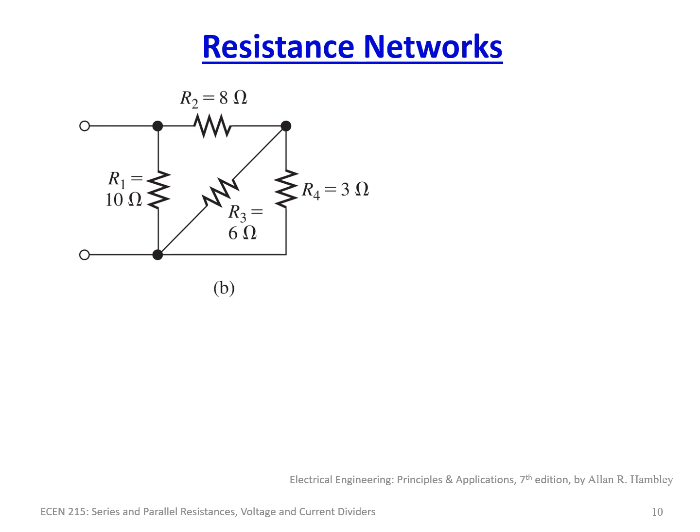But in the end, it's only series resistance and parallel resistance. So a way you can always deal with this is you can always label the nodes. So if you ever get confused and think, well, who's connected to what? Label all the nodes, and anything that's in a common pair of nodes, those are in parallel. And anything where the nodes are joined together, you're going to add as in series.